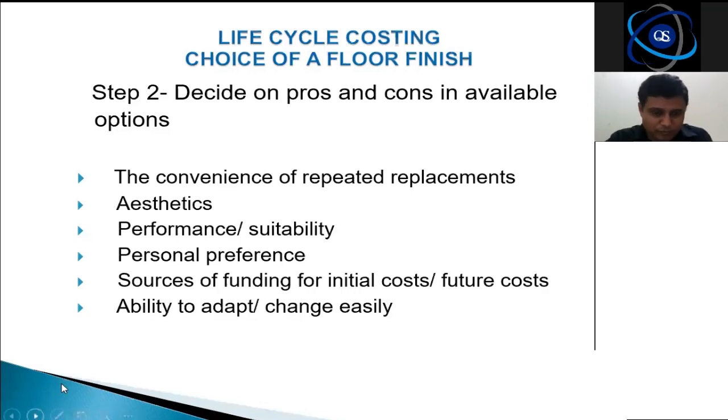Right. Then the personal preference, sources of funding. Now, if you cannot fund, there is no point. Maybe your initial cost may be very high in establishing. For example, if you are talking about having autoclaved aerated blocks, perhaps you might think about having that autoclaved aerated block machine in place, because you are talking about hundreds of buildings that you are going to build in the future. But if the client doesn't have that particular budget at this juncture, it is not a feasible option.